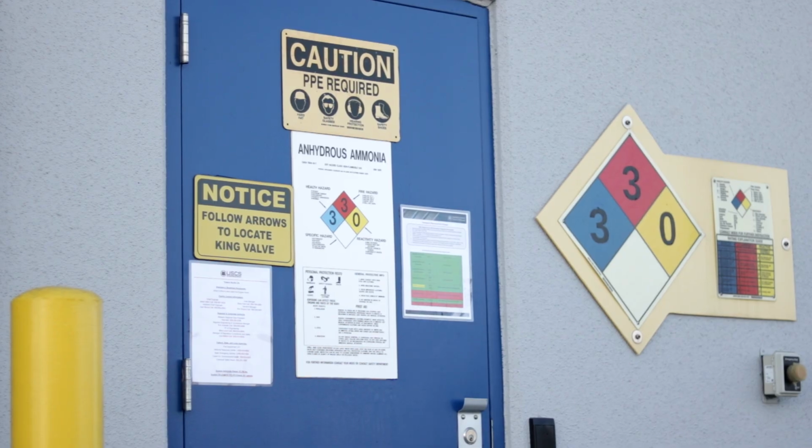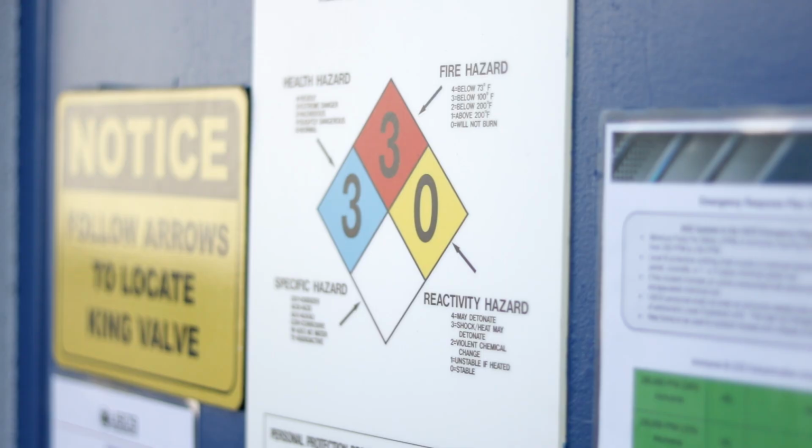Burst piping, valve failures, or ruptured components are examples of equipment failures that can result from trapped liquid over pressure. The refrigerant release is dangerous because the discharge will be high pressure and may be toxic, flammable, and extremely cold.